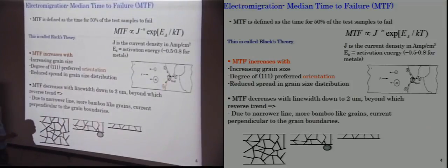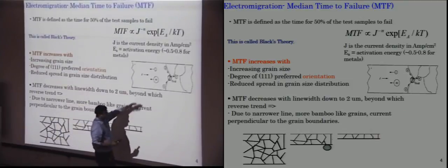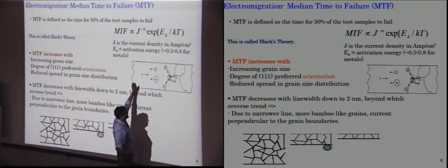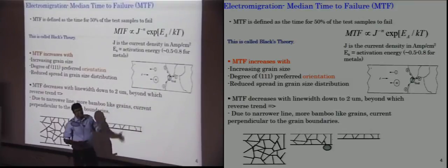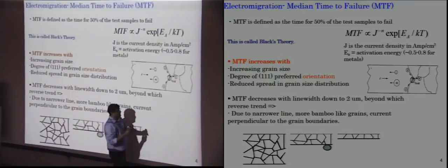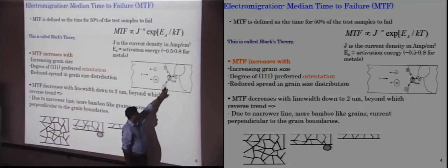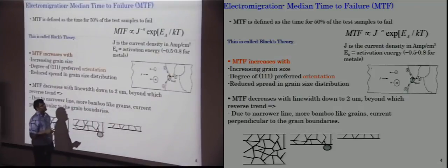So the activation energy for diffusion at the grain boundaries is very low. Another factor that is also important is the electron wind. When it is passing through the bulk of the lattice, the amount of interaction between the electrons and the lattice is not that much of a problem. It's just over here where there is asymmetry and discontinuities that the electromigration effects are felt higher.